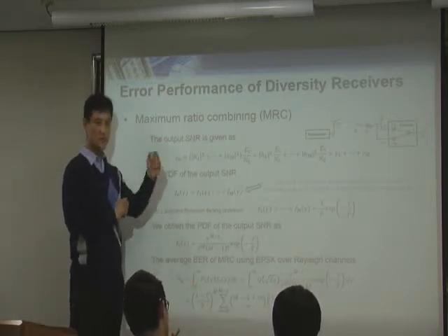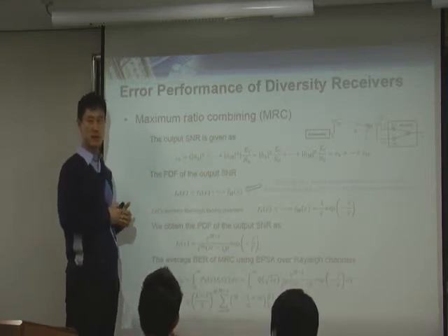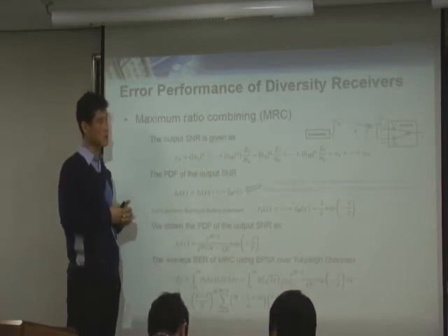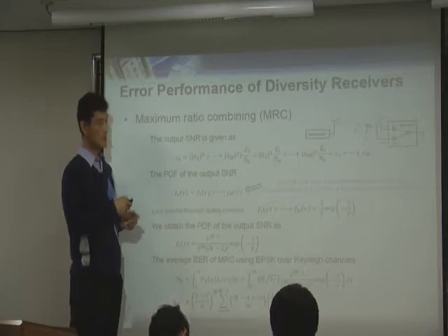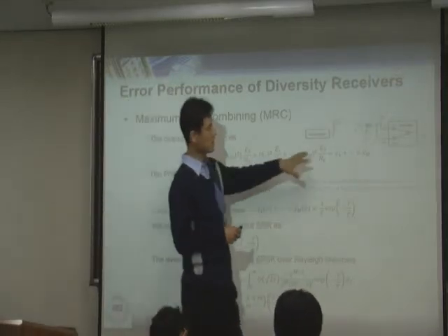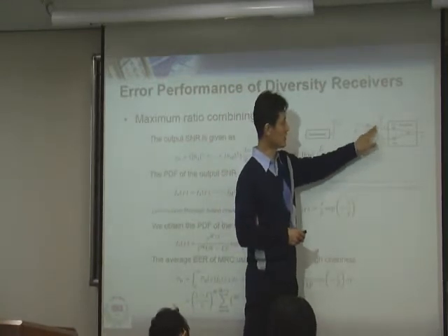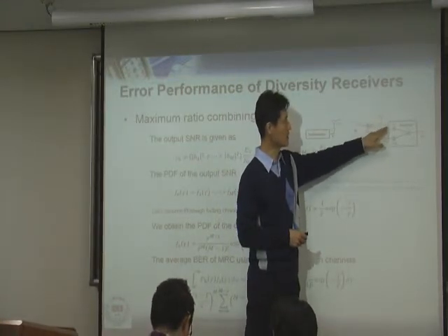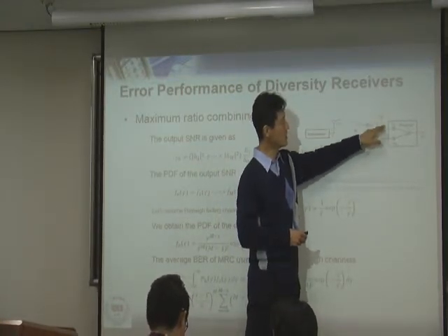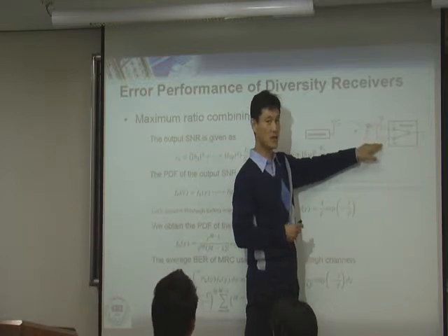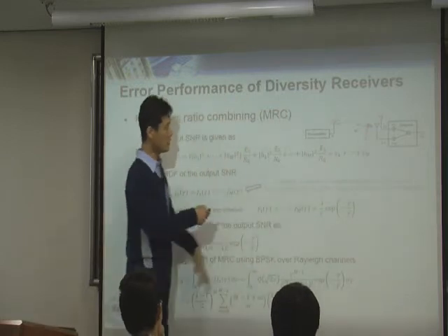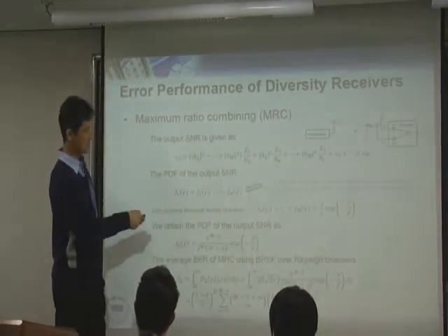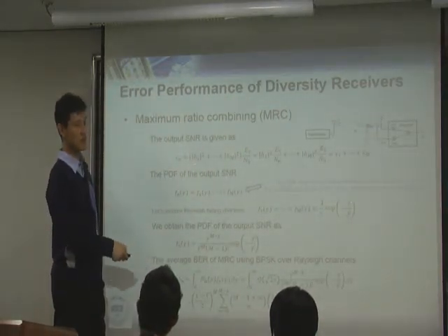Maybe some of you have some experience with CDMA. When you look at a CDMA system, you'll probably see rake receivers. A rake receiver uses MRC. The difference here is that in this case, I use each one as an antenna; we are thinking about multiple antennas. Instead of multiple antennas, if you think about multiple rake receivers, then all the other mathematical analysis applies exactly the same way.